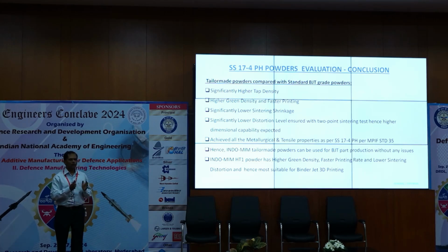And there is also a lot of scope for optimizing the powders, especially the compositions and the particle size distribution. We are going to work on a similar methodology for laser bed methods, because in the laser bed method, the initial packing density, we think, may help in reducing the support structure. If you are able to minimize the support structure, a lot of the post-processing operations can be avoided. So we are going to work in that direction. Maybe the next time we can present on that. But this is the work we have done till now.